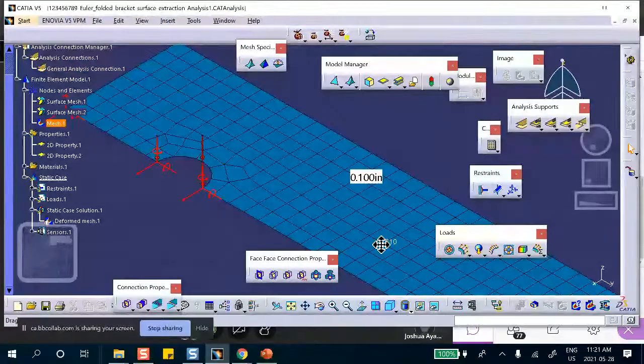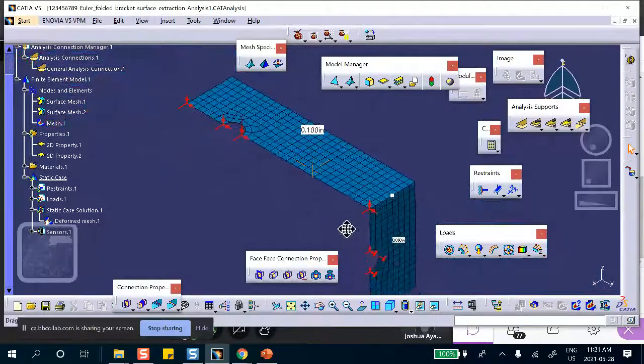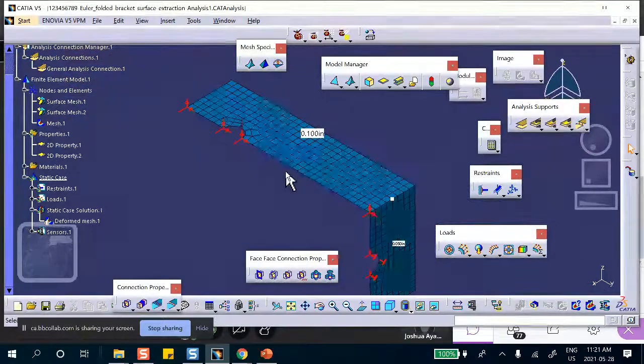Are these better elements than the one that we have been using? Yes. Do I expect you to use these? No. Why did I tell you that? Because in the book, there are a few occasions that I take you to the advanced meshing tool to get a fancier mesh. I don't want you to panic. Where did that come from? This guy didn't cover it. Anything that's done here, you do it with this horrible 3-noded or 6-noded element, parabolic or linear.